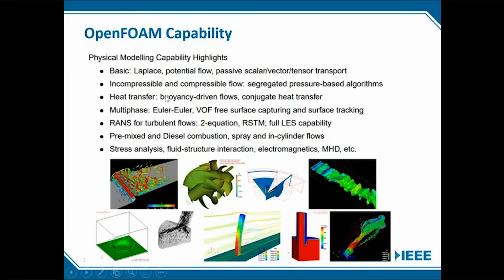For example, my research here at Purdue is regarding multi-phase flows, but at very low Reynolds number. So I took a Euler solver and made a copy of it, and then I went into the governing equations. I added or subtracted some of the terms which are not relevant to my particular problem, and then I'm solving this equation. So this is why OpenFOAM is really helpful. If you know your fluid mechanics well, if you know your governing equations well, and if you know C++, you can do anything.